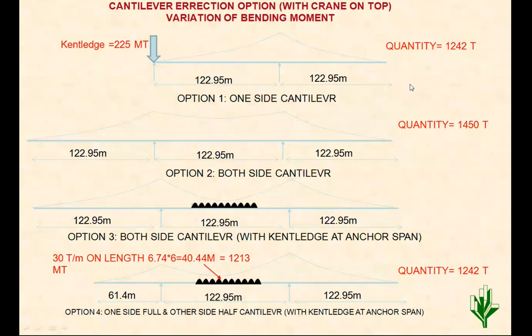But in case of cable stayed bridges, this redistribution doesn't take place. So whatever deformations will come, those will be locked-in stresses. So in case of cable stayed bridges, construction stage analysis has to be done. In case of these trusses, the service analysis can be done separately and the construction stage analysis can be done separately, because the behavior of the two stages is entirely different and they are not connected to each other, because the stress is redistributed after removal of the linkage.